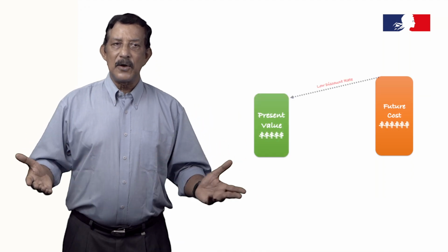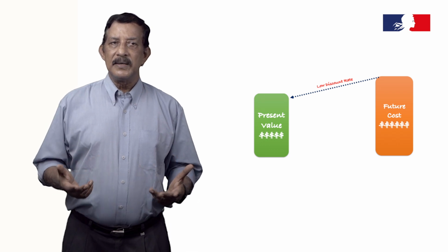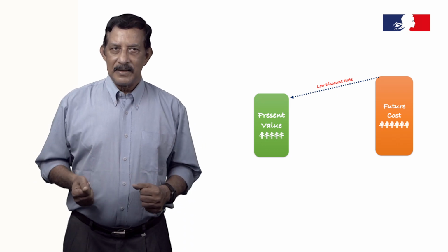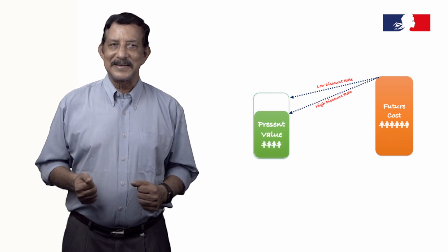Overall cost assessment of a building is particularly interesting when exploring solutions that must be compared in order to select the one that gives the minimum cost or maximum savings. In order to be able to add and compare cash flows that are incurred at different times during the life of the building, future costs need to be converted to present values by discounting them to the present. The interest rate used for discounting is a rate that reflects an investor's opportunity cost for money over time. A high discount rate means little importance given to future generations and vice versa.